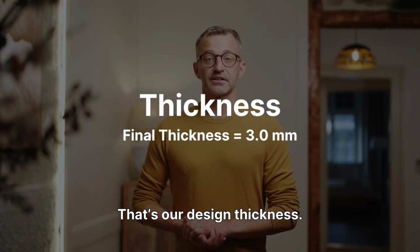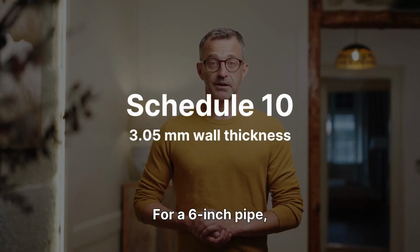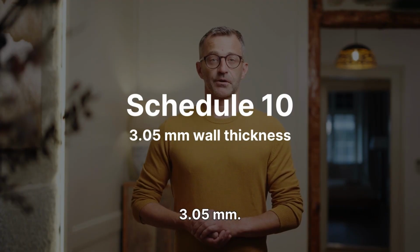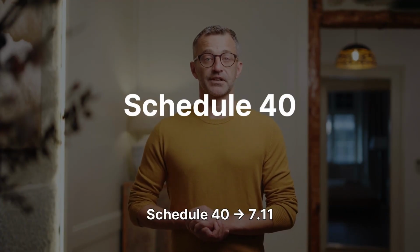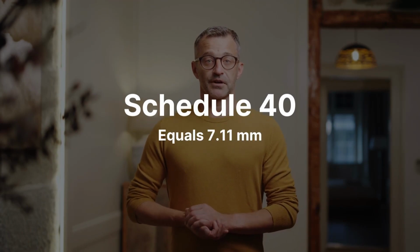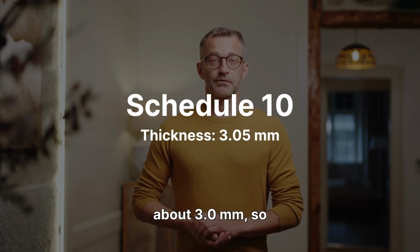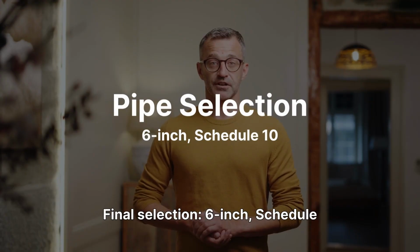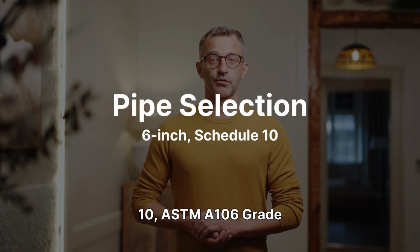That's our design thickness. Next, we check standard pipe schedules from ASME B36.10. For a 6-inch pipe, the available wall thicknesses are Schedule 10, 3.05 millimeters, Schedule 20, 4.78 millimeters, Schedule 40, 7.11 millimeters. Our required thickness is about 3.0 millimeters, so the nearest higher standard is Schedule 10. Final selection: 6-inch, Schedule 10, ASTM A106 Grade B pipe.